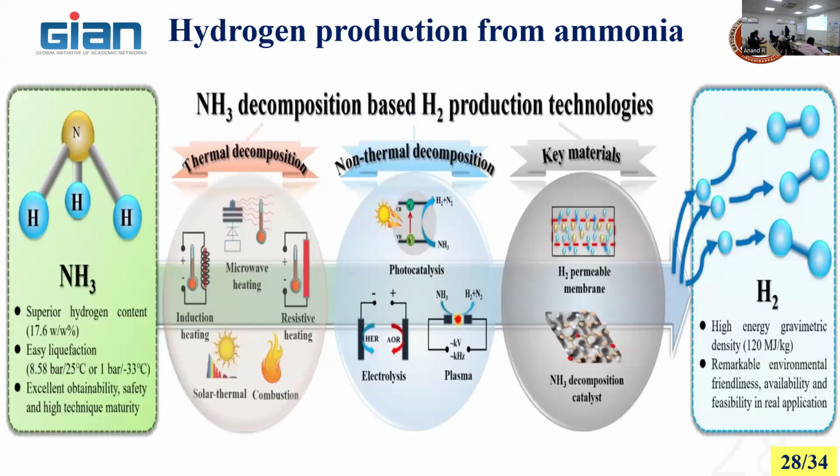So ammonia decomposition based on hydrogen technologies, right? There are different technologies available. But for thermal decomposition, I said, you want only heat. So you can produce it from resistance heating, electrical heating, microwave heating, induction heating, solar energy, or combustion. But I need that temperature and pressure, so you can provide that temperature by any mode of device.